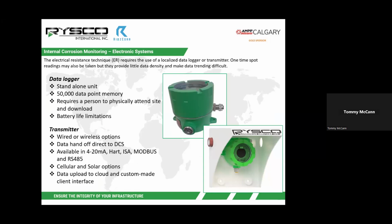And how do we take those readings from those ER probes? Again, two main common types. You need to give power to the probe, and you need to store the data. The data logger is a standalone unit that you have to physically go to. The one we produce can store 50,000 data points. There are obviously some advantages to that, but a lot of the time in remote facilities, that can be a disadvantage.